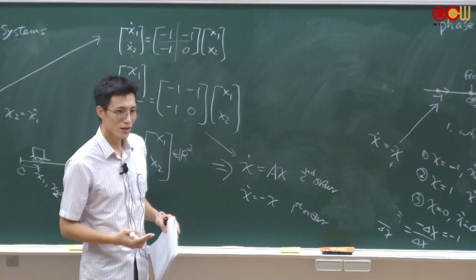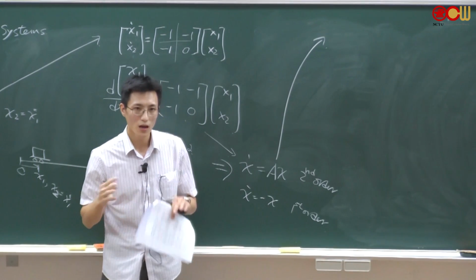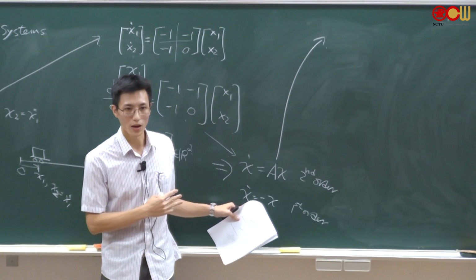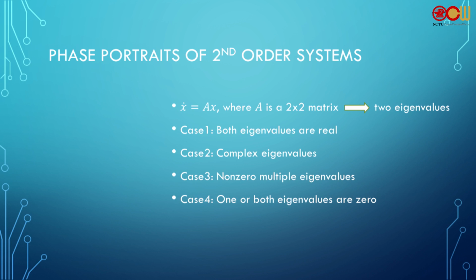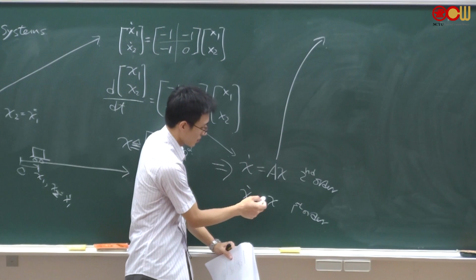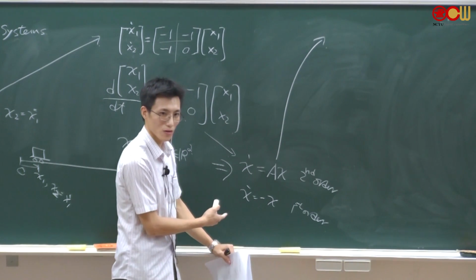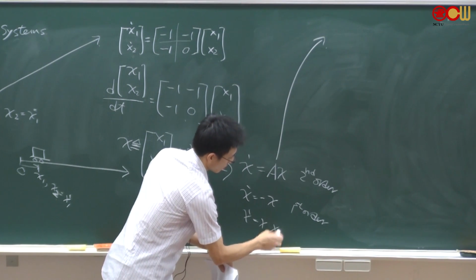So at this time, the eigenvalue pops out. Here, it's easier to tell this system is stable, right? Because the coefficient is -1. You can either use that criterion, the stability of the equilibrium point, or, for me, it's easier to tell that if the coefficient is -1, it is stable. If the coefficient is positive, it's unstable.